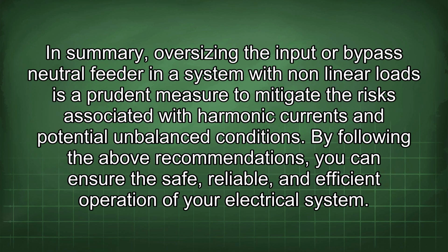In summary, oversizing the input or bypass neutral feeder in a system with nonlinear loads is a prudent measure to mitigate the risks associated with harmonic currents and potential imbalance conditions. By following the above recommendations, you can ensure the safe, reliable, and efficient operation of your electrical system.